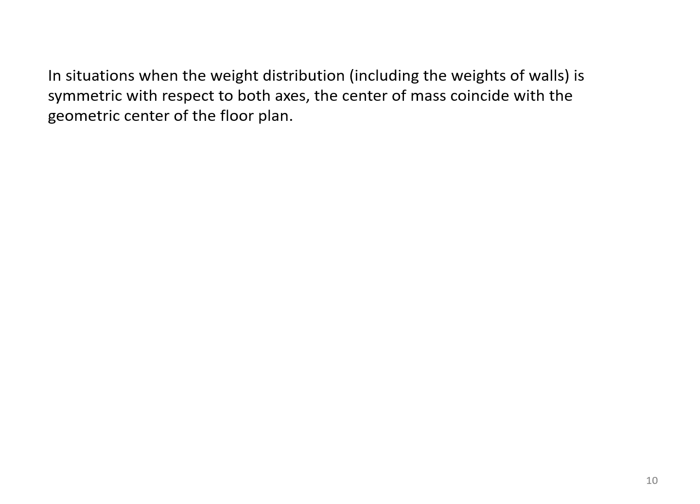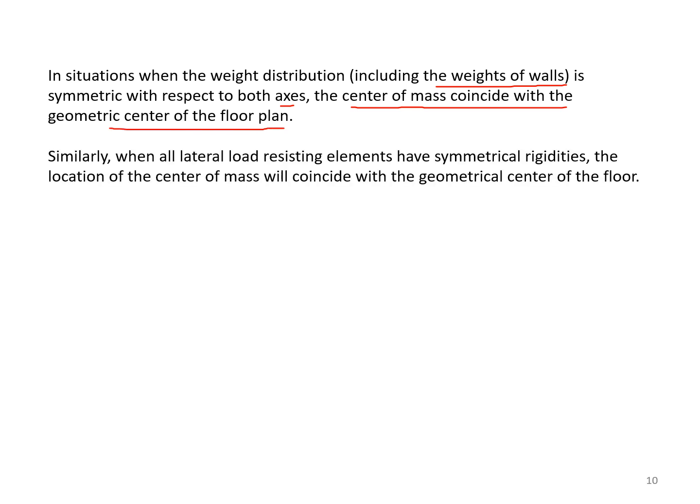In a situation when the weight distribution, including the weights of the walls, is symmetric with respect to both axes, the center of mass coincides with the geometrical center of the floor plan. Similarly, when all lateral load-resisting elements have symmetrical rigidities, the location of the center of rigidity will coincide with the geometrical center of the floor.